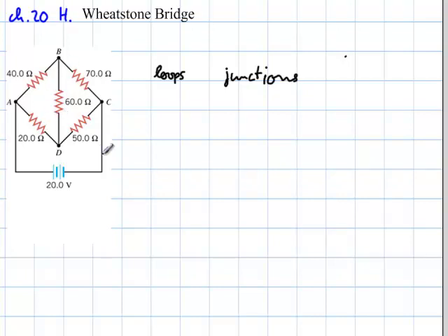There's also a 6th one here, which is the current that flows through here, but I don't want to introduce that 6th unknown, because once I have these 5, I could figure out what the 6th one is. So we'll just leave it out. We have 5 unknowns, the currents that go through here, for which we technically only have to determine this one, but there's no way around it. We have to find equations that simultaneously compute all 5 of them, and then we single this one out later on. We need 5 simultaneous equations.